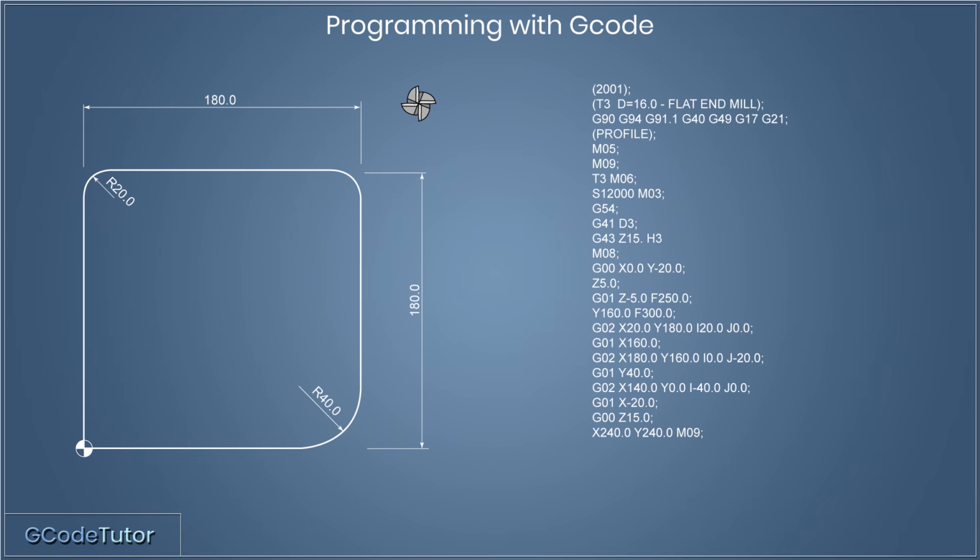With G00 still being active, we can now move our cutter back to its home position. Now this is the machine's home position we're talking about here. So I've declared that as X240, Y240. We can also add M09 to turn off the coolant at this stage. Now we can only add one M code per line. So normally if we have multiple M codes we wish to turn on or off, we would have them on their own separate line, but it's totally acceptable to have one M code on any other line of code.